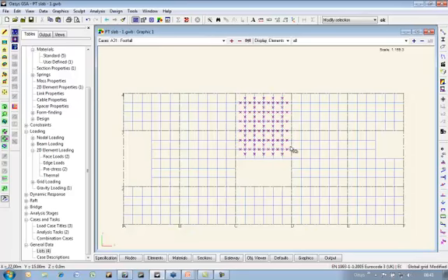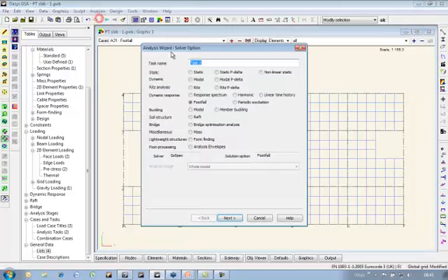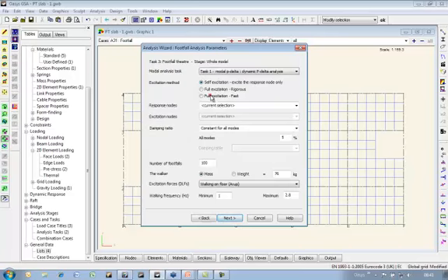So this area here, I'm going to call this my operating theatre, and I can look at the response elsewhere. So I'll do a new analysis task. Theatre. Response nodes is the theatre. Excitations all.